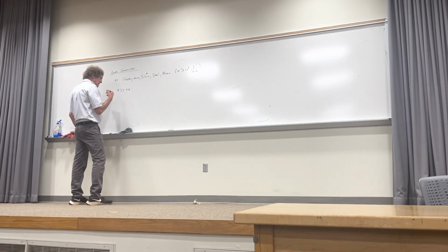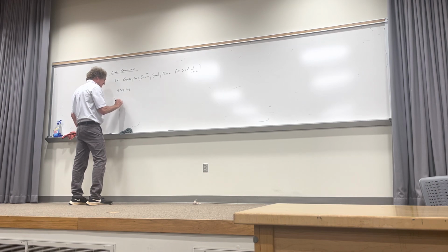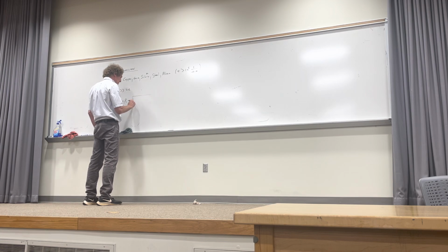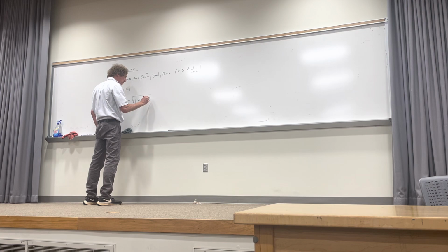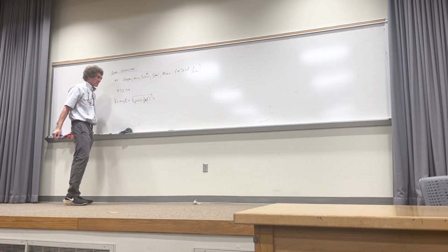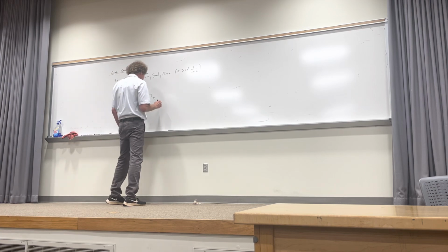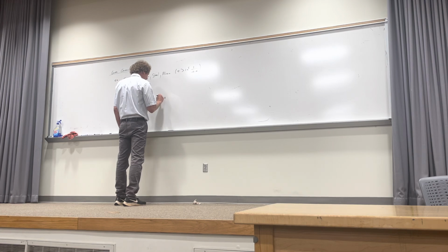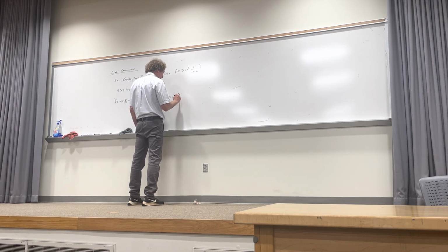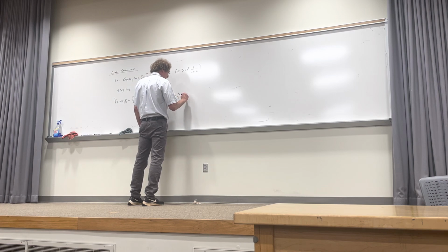And you take a look at material parameters. First, when you look at the propagation constant, it's alpha plus j beta. If it's a good conductor, it's the square root of j omega mu times (sigma plus j omega epsilon). But because it's a good conductor, we can get rid of this term. And we just say this is equal to the square root of j omega mu sigma. And that's really (1 plus j) times the square root of pi f mu sigma.